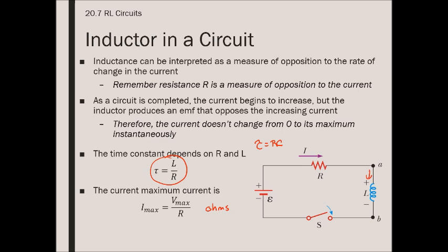So what's going to happen is we're going to start going through the circuit, and since there's no current, there's no voltage drop across the resistor, so the voltage drop there is about 0. That means to get back down, if this is charged to like 6 volts, then if the voltage drop across the resistor is 0 because there's no current, then this is also about 6 volts.